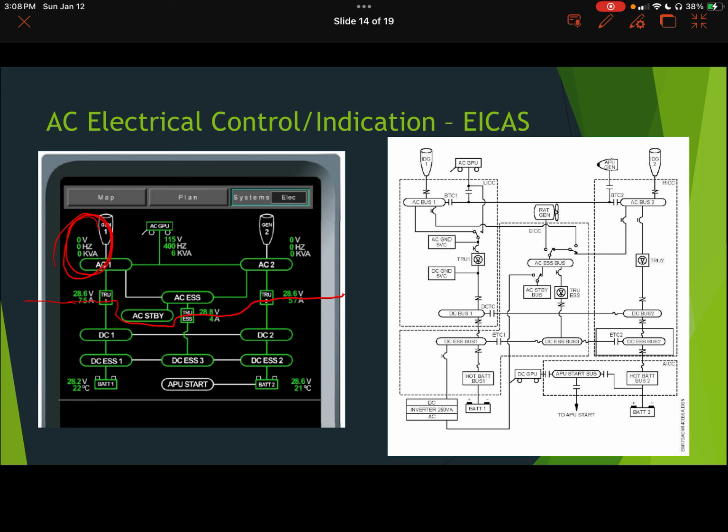Rather than just looking at amps, or looking at power in the form of watts, kVA is volts times the amps being drawn, divided by 1,000. It also takes into account things like reactive and apparent power, which is a vector calculation based on the fact that inductive loads are going to drag AC phasing out of sync.